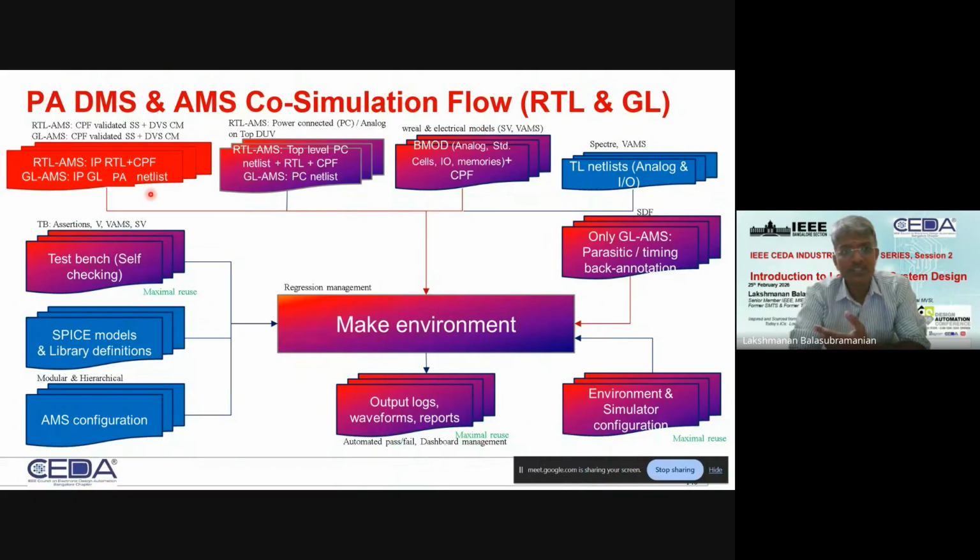And all of this is associated with the CPF or UPF power intent. For each of these different kinds of power intent, for analog and mixed signal and hard IPs, you will use black box power intent or a macro CPF or a power model UPF.